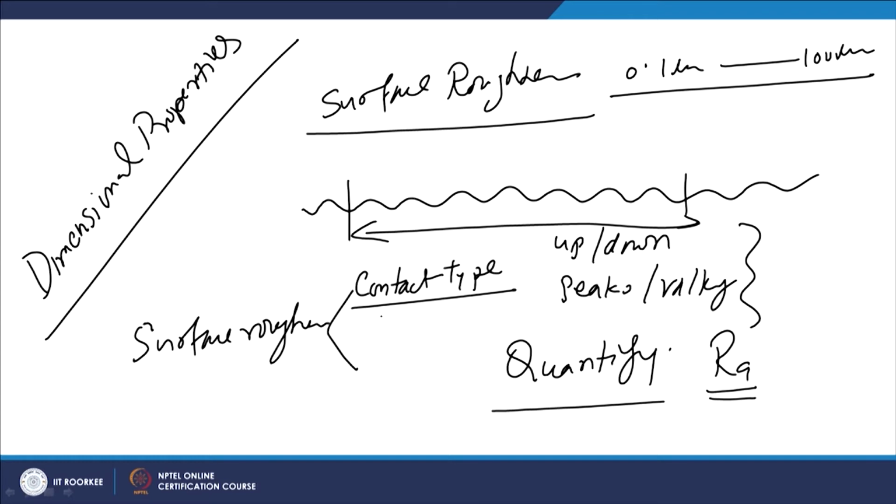And in this category, basically we use a stylus based method, where the stylus is moved over the surface of the component which is to be quantified with regard to the surface roughness.